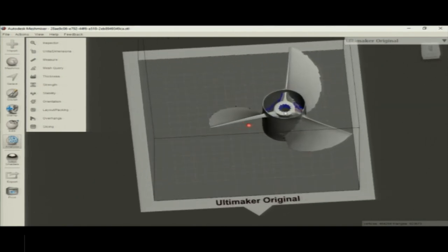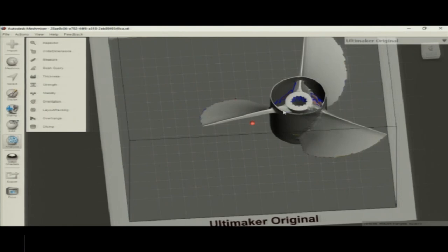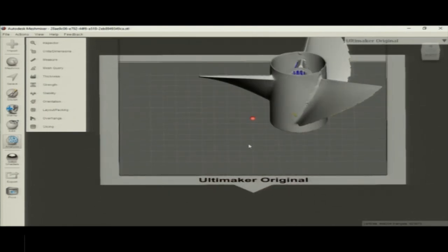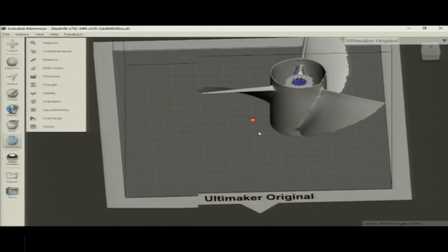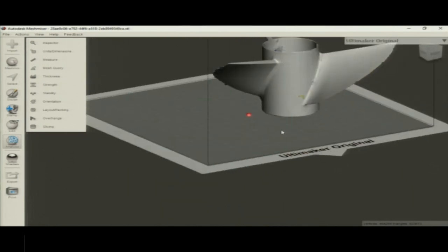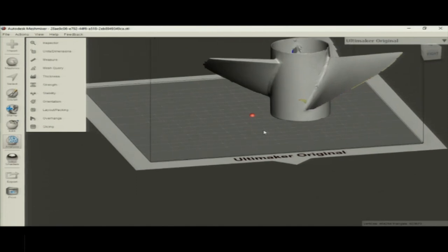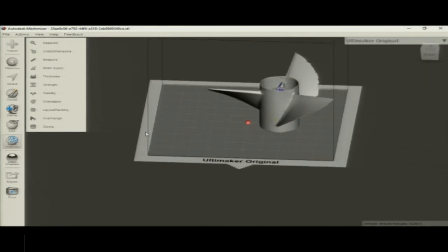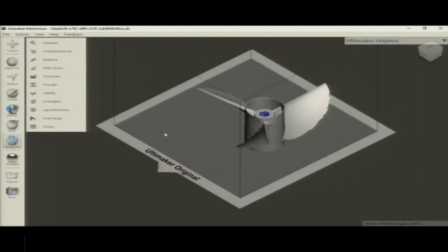You can see here, this is a very fine boundary which is placed over the print bed, and this very small thickness wouldn't have strength to stay on the bed, so it might pop off. So we need to consider all of these conditions like brim or raft, what is to be put in here.